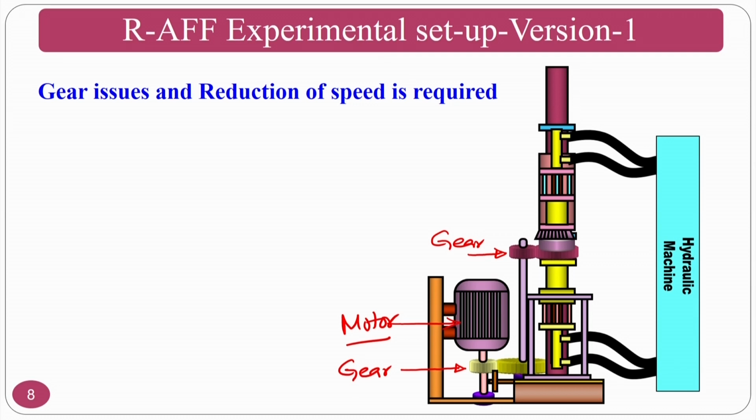This was designed as part of the PhD program at IIT Kanpur. The problem is that if you are rotating at high speeds and your gear materials are not proper, or you do not have the proper gear reduction ratio, then the teeth will break instantaneously, after a few experiments itself. If the setup goes bad in a few experiments, it will be very difficult to proceed.